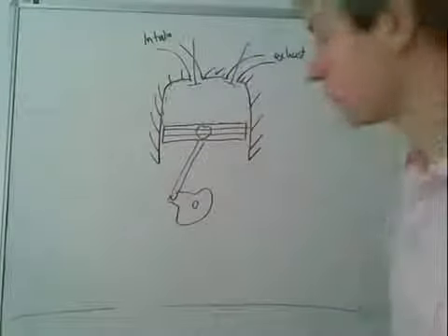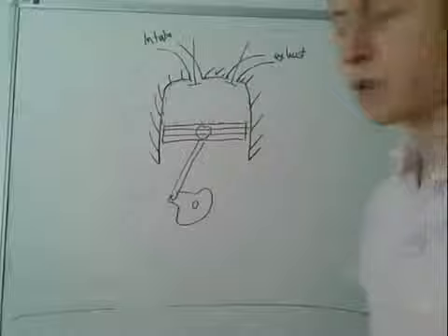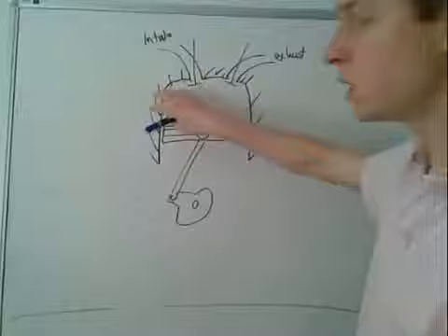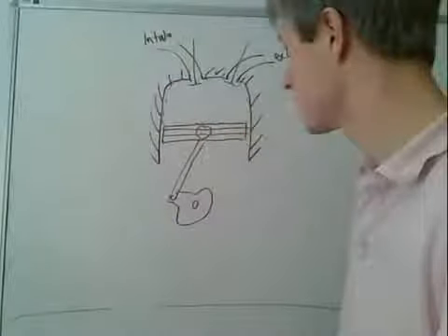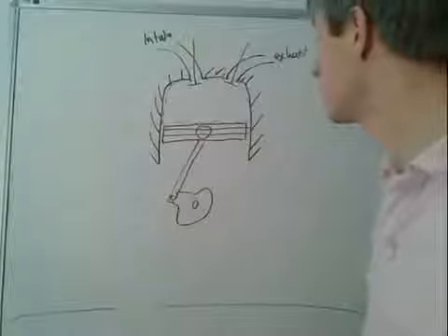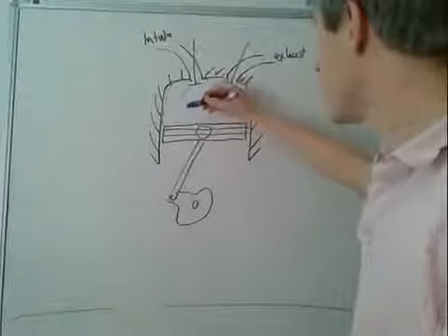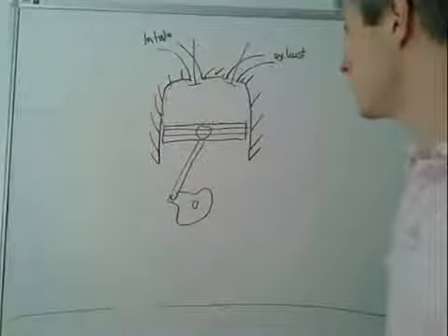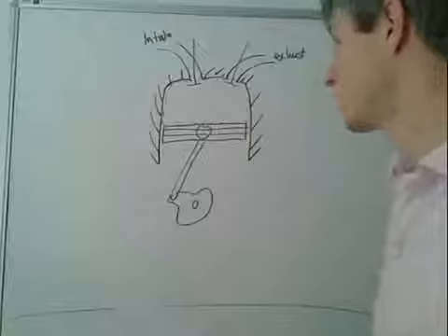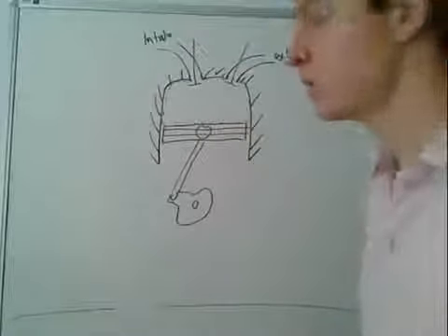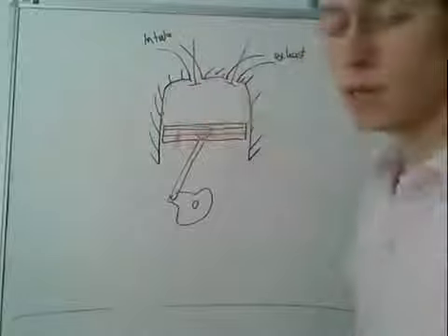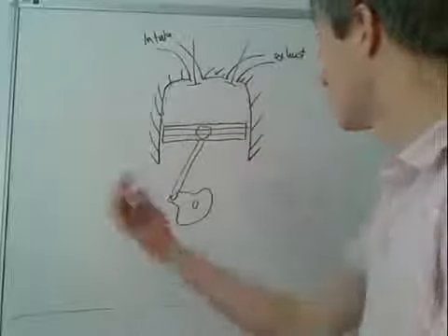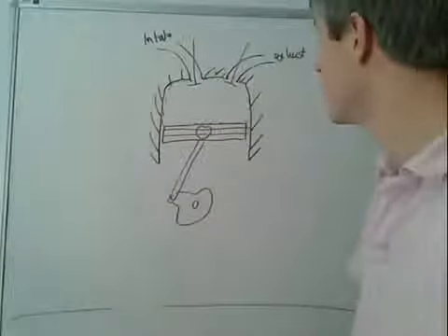It's exchanging mass. So what are the heat and work flows in this case? Well, if the combustion products are hot, or hotter than the metal, there'll be heat flux into the metal. So that's a heat exchange. Now, is there a heat input? Well, strictly there is not a heat input to a combustion engine like this. There's an input of chemical fuel energy. So actually chemical energy gets convected into this system when the intake port is open, and the fuel air mixture is inducted.